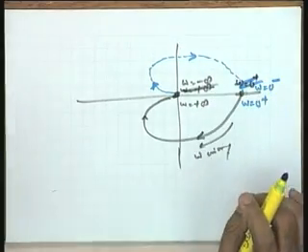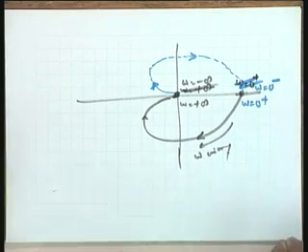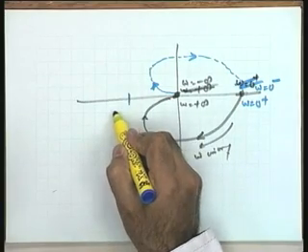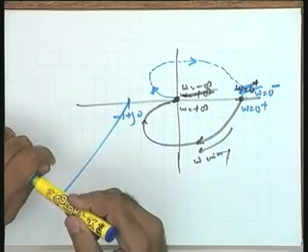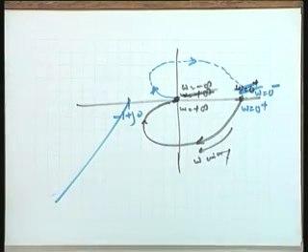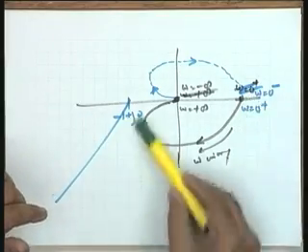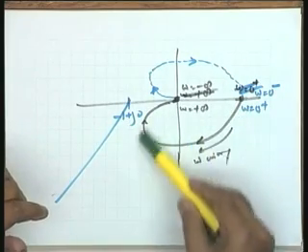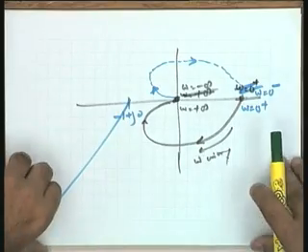This gives me the complete map of the Nyquist contour. The complete map of the Nyquist contour is available. Consider the minus 1 plus j0 point, a point in line in any direction, there is no intersection, and hence the system under consideration is a stable system. Okay. Now though this particular problem has taken a little more time, actually in any problem you are only interested in the frequency response of the system, that is all. Once the frequency response is available, you can quickly get the answer to the problem.